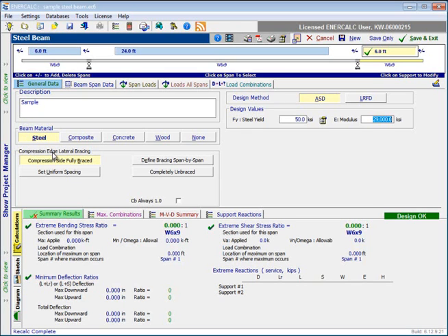So in the present version of Structural Engineering Library, it interprets these settings to be applicable wherever the member is in compression. Naturally, in a member like we've defined here, that can mean that there are compression locations in the top flange in some areas and compression zones in the bottom flange in other areas. So whatever we set in this compression edge lateral bracing category will be interpreted as being applicable wherever the member experiences flexural compression.